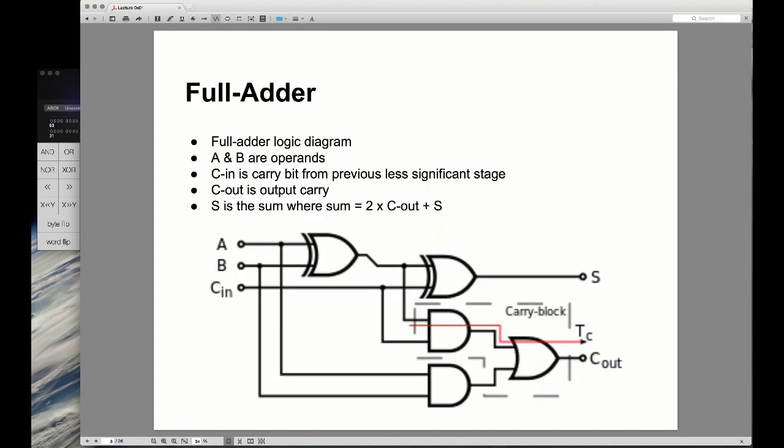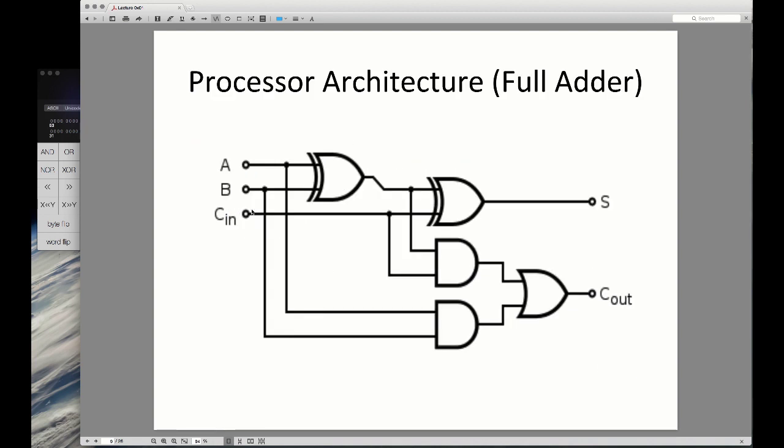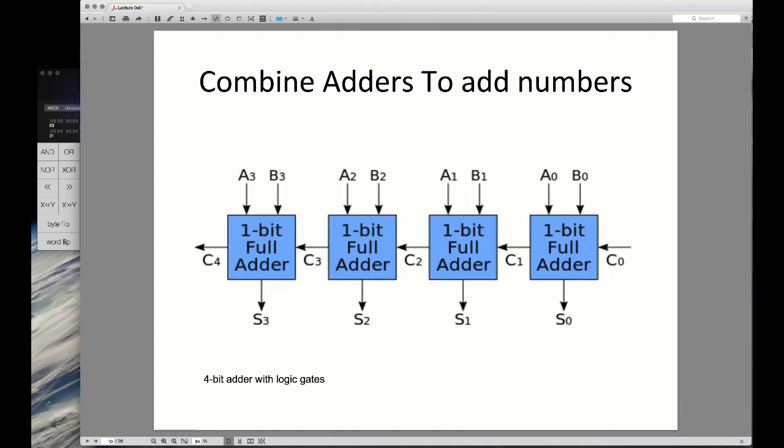Right, we talked about the adder, a slightly different representation of that. This is more of a logic diagram, and again, you may have seen these in your discrete math course. A and B are operands, A and B are inputs, as well as the carry, and then we have the sum, and we have the carry out. And so we could do an example here, just like we did previously, where we have our input 1 and 1, and let's say that our carry in is 0. 1 plus 1, that sum would be 0, and our carry would be 1. And so that is the basic logic that is implemented using these digital, electronic components, down at that lowest level, to actually build the CPU.